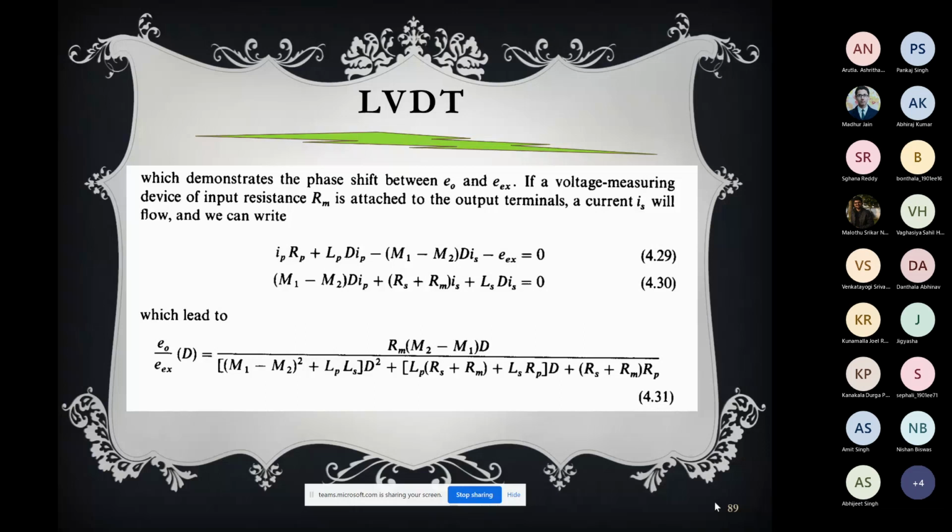So at low frequency, when phi tends to plus 90 degrees, and at high frequency... At low frequency all the poles will not contribute, only the zero will contribute, and there is a zero at origin, so you will get a plus 90 degree phase shift.